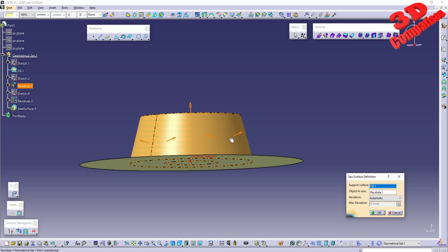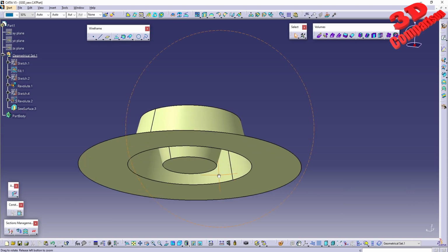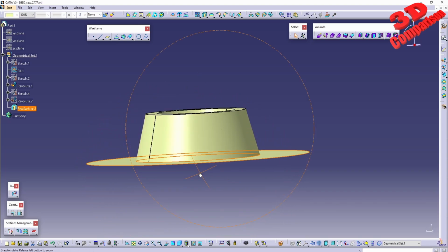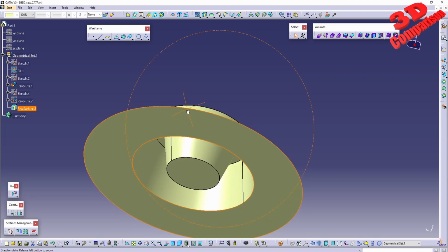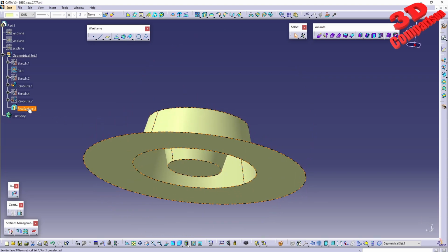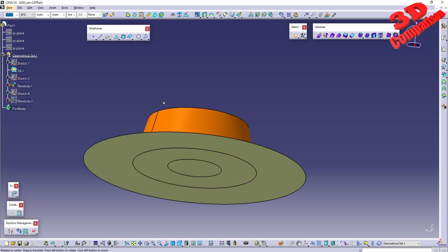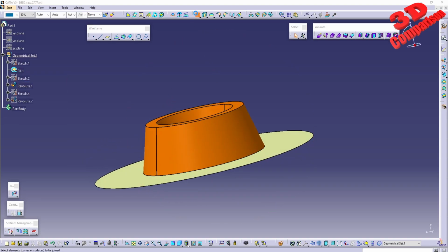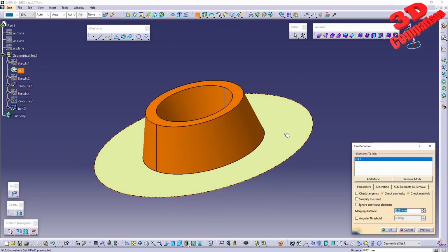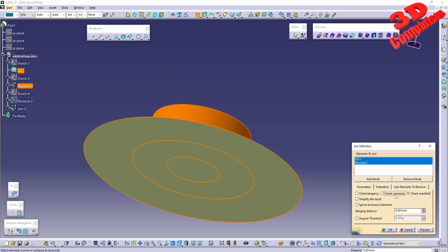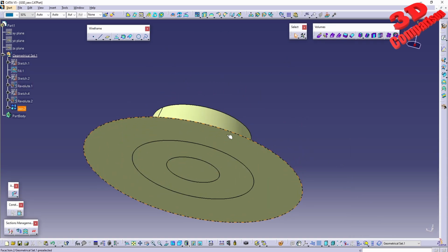And if I will reverse the orientation of those, now we're gonna have that inner section not defined, but the one in the middle will be filled, and also the exterior. So this is how you can use that SU surface. If I will just delete that for now, and I will re-enable the first fill, and if I will do a join between the bottom fill and the revolve, if I will disable the check connectivity over here, I will click OK.